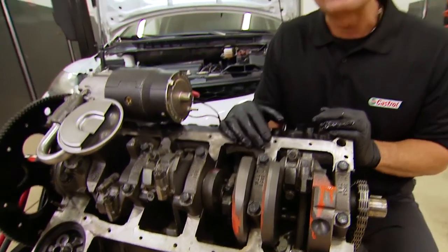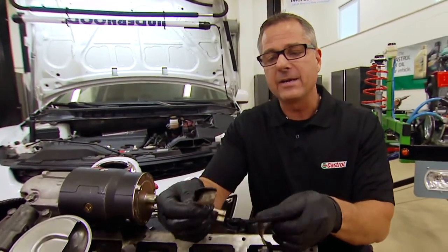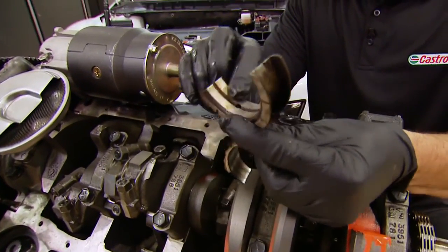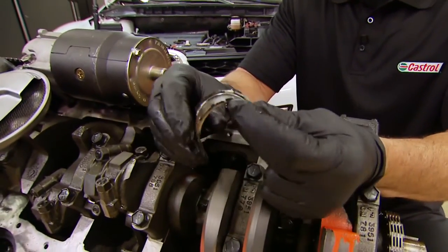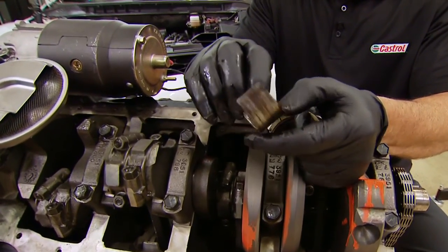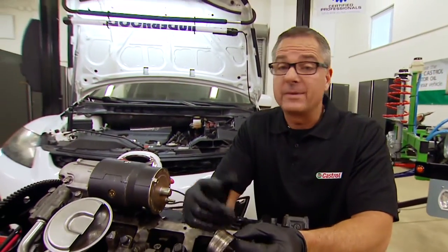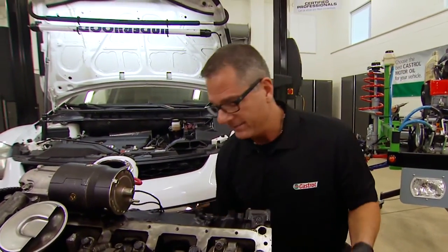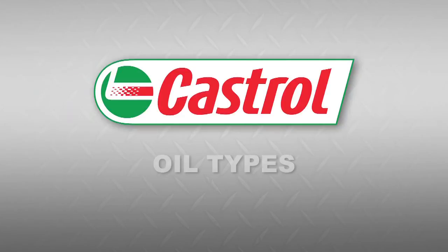Now, obviously there's no oil pressure in this engine, but there would have to be in order to support these bearings. You can see right here, I have an actual thrust bearing. Now this bearing here, this one's in pretty good shape. You can see here, has a little wear pattern, but this has been maintained well. Now this one here, on the other hand, not so much. You can see here where the actual bearing actually got worn out. This engine here was starving for oil. Maybe it had the wrong oil, or maybe the customer wasn't informed on what they should put in their vehicle. So that's important. That's your role. You have to go out there and educate them on oil basics so their engine doesn't end up like this.